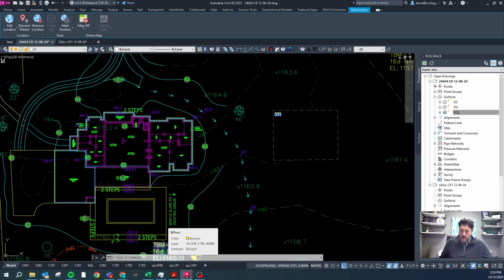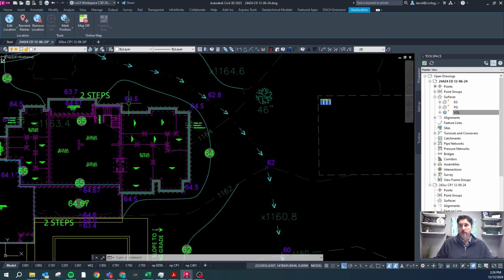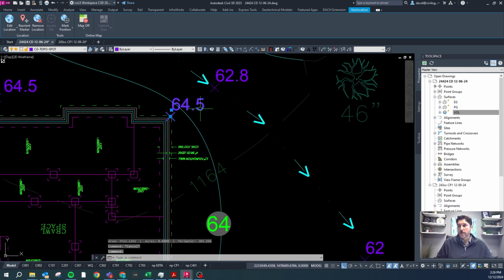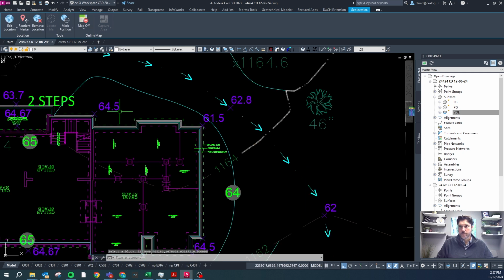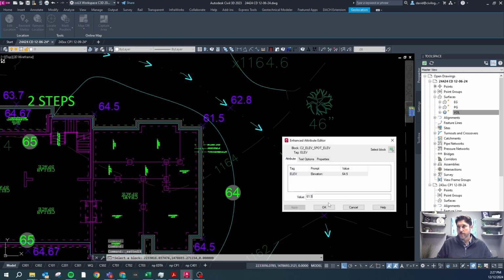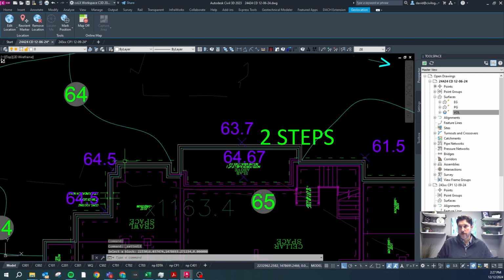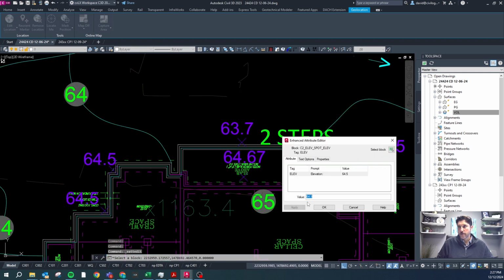So 0.08 acres times 1,600. So if we raise the house 1 foot, or we lowered it 1 foot, that'd be 128 yards, but we're lowering it 3.5, so that's about 450 yards. So that should be fairly accurate, but now we need to fix these spots. So these spots are going to be 61.5. So we'll go around, fix this real quick.